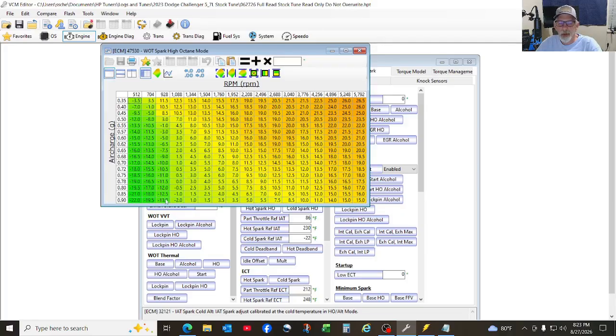People don't understand what it's for, but that's exactly what it's for, because you're going to go into deceleration fuel cutoff. You've got to get that timing out of there because there's going to be vapors in there, and if the timing is still there, it's going to ignite. And if it ignites because it's a much thinner, leaner mixture, you're going to get knock and possibly damage your engine. So wide open throttle is, I mean, you're coming from here and going to here, and it's just like you're here and then all of a sudden you're here, boom.